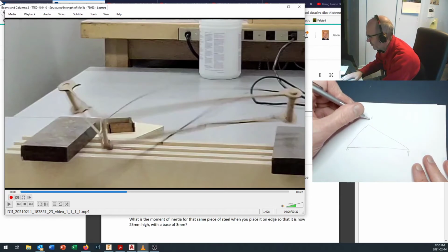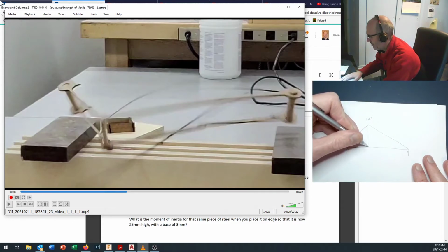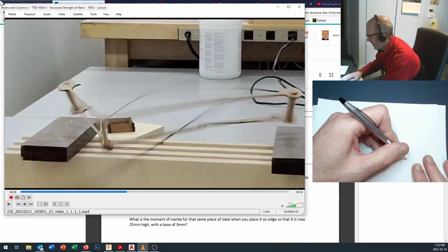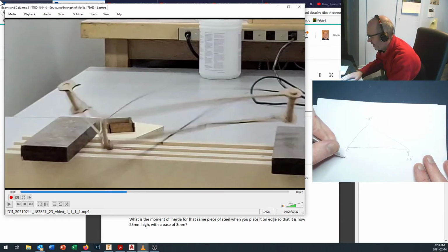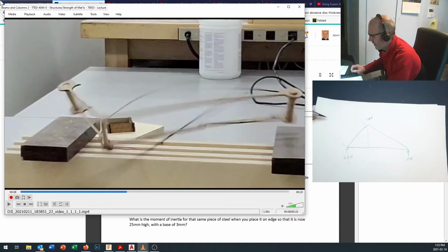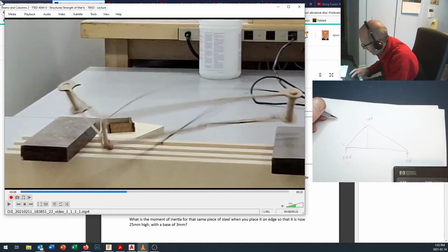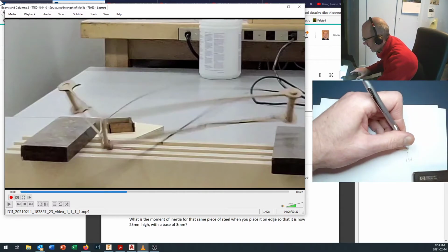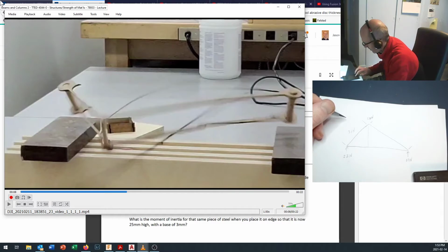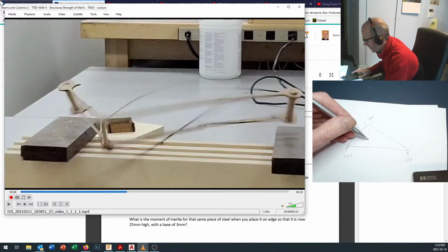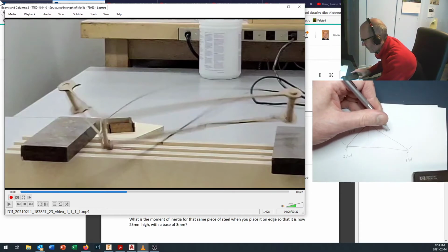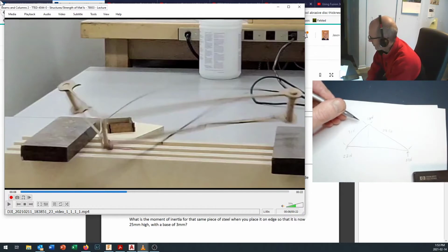Actually, if we say it's 33 newtons, those calculations get really easy because this is 1/3 of the mass because it's 3 times the distance that it's located at. So we'd have 11 newtons out here, 22 newtons right in here. This member right in here was actually supporting, again, this is 1.41 times as long as this is right here, so we can start calculating this a bit more quickly. This was supporting 31 newtons, and out here, this was 11, 2.23 times as long right here as it was right there, 24.5 newtons.